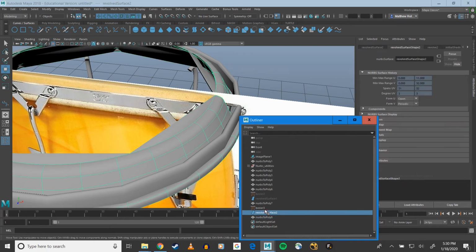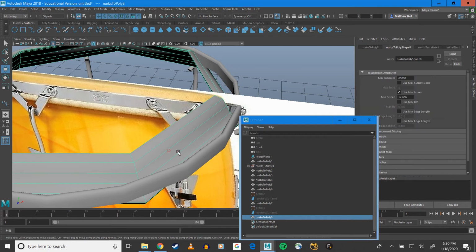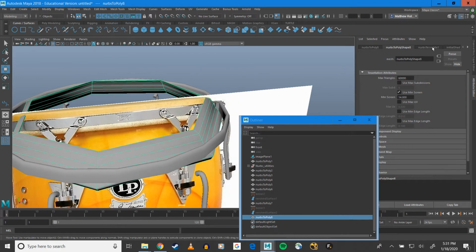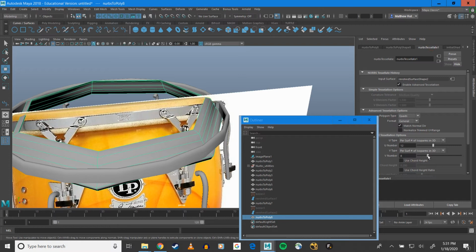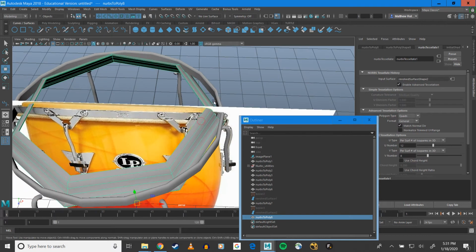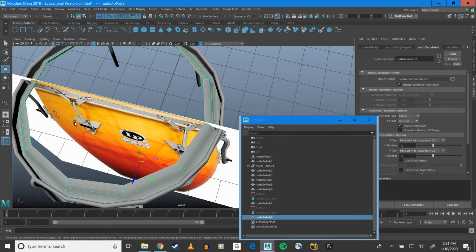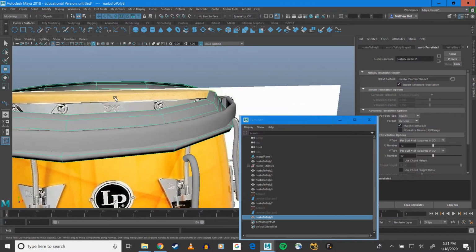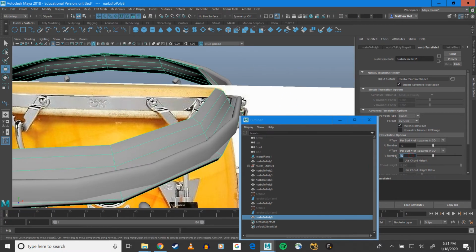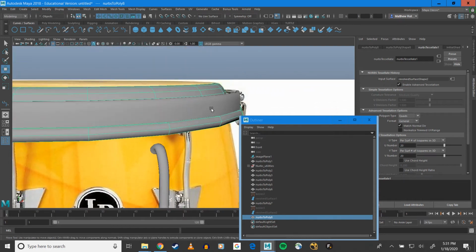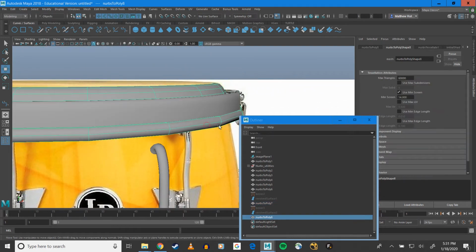So I'll hit convert NURBS to poly. Let's check my polygon object that I'm working with here. You can see it's not really as high res as I want it to be. So my V number, which is giving me my vertical edge loops in this case, I want to probably set that to be at least 12. I'm rather partial to 12-sided cylindrical shapes, but I can also go like this and do 20 and 20 if I so desire, similarly to how we did this.